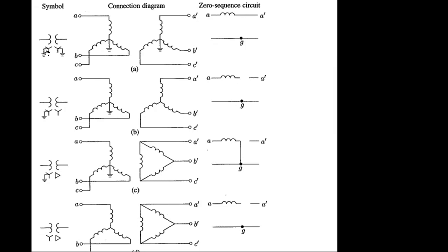Actually, how to replace that zero sequence transformer circuit to generate the zero sequence equivalent network, because you have generator, you have transformer, as well as you have line. For line, you can replace easily by equivalent reactance information. For transformer, you have to use the proper zero sequence circuit based on internal configuration in terms of primary and secondary.